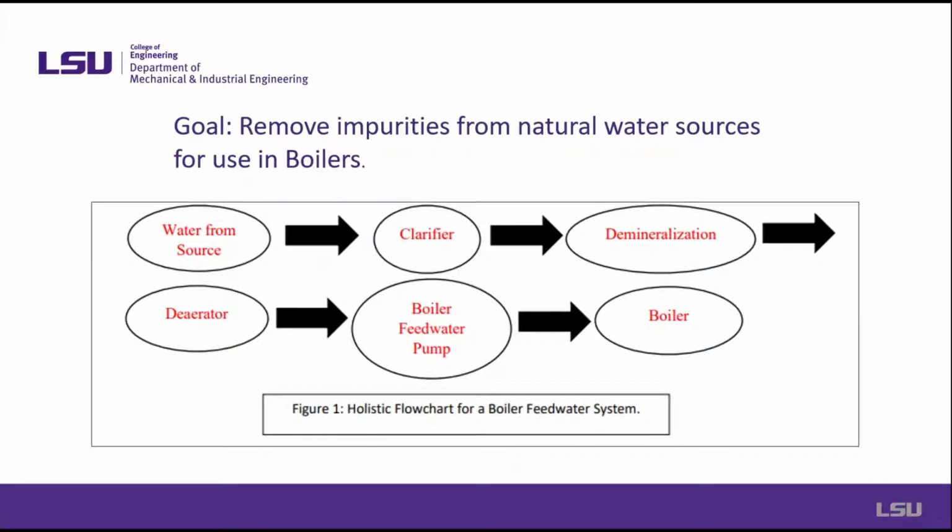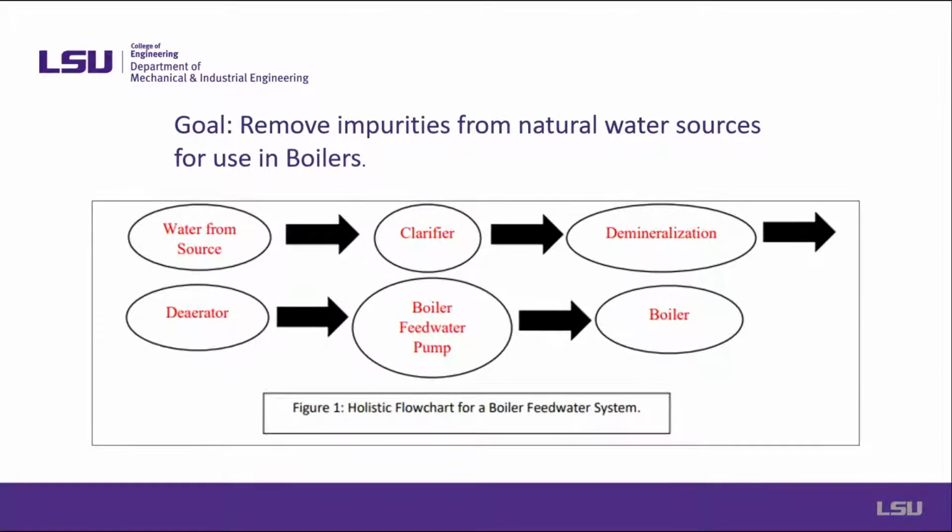The goal of a boiler feedwater system is to remove impurities from natural water sources so that it may be used in boilers. A facility may produce steam with water that comes from lakes, rivers, and streams. This water contains suspended matter. A clarifier is used to remove the suspended matter from the water.